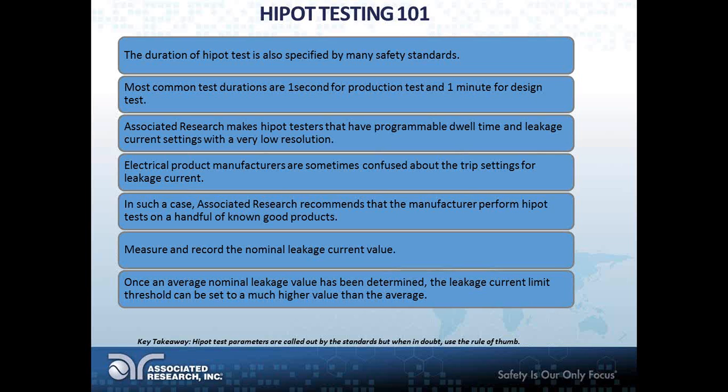When the test voltage is applied for 1 minute, the Hipot meter can easily be monitored to see if the output voltage has varied or not. And for a 1 minute test, the operator has enough time to adjust the output voltage to the correct level if necessary.